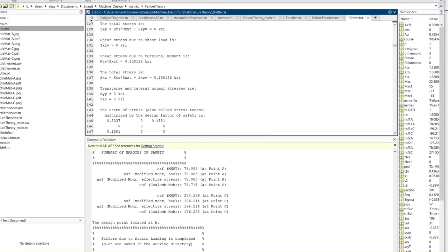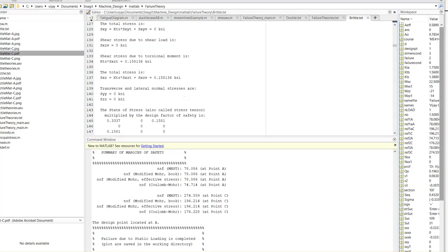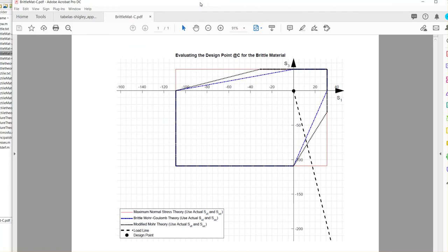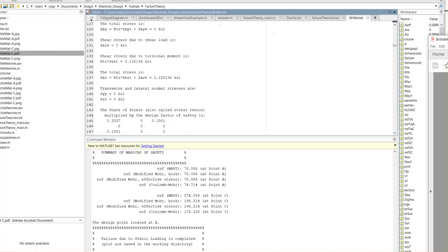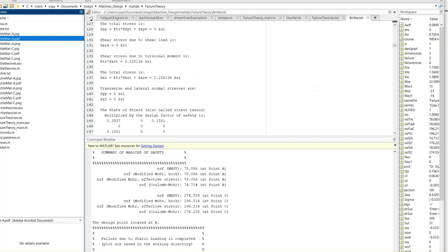So this is a very good example in which you can see that because one side was negative, let me explain to you what's really going on in the problem. So this really doesn't mean anything, okay? Absolutely nothing because I don't know the value of f. But what's happened is in one case it is in compression, right? And the other case is in tension.